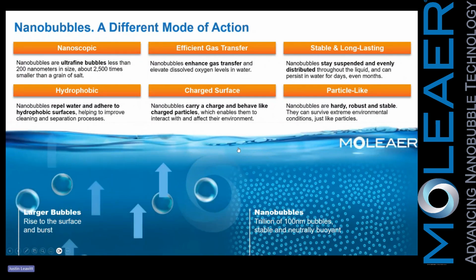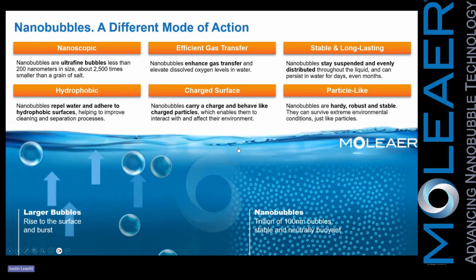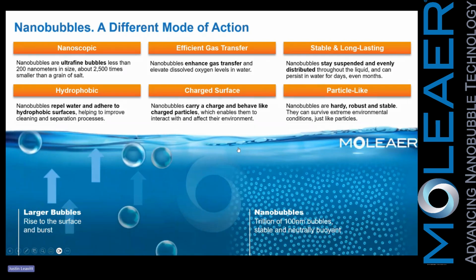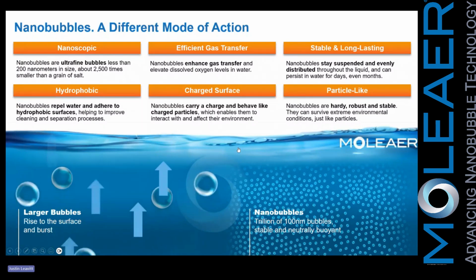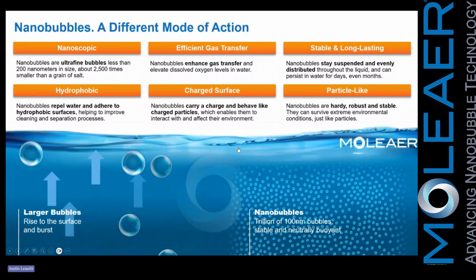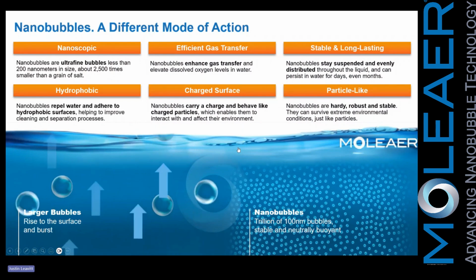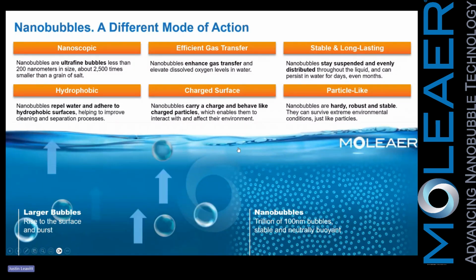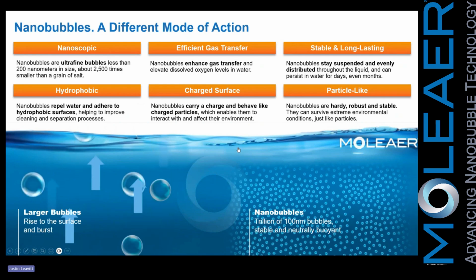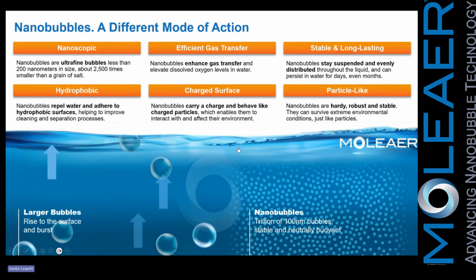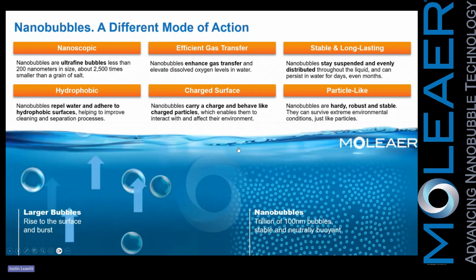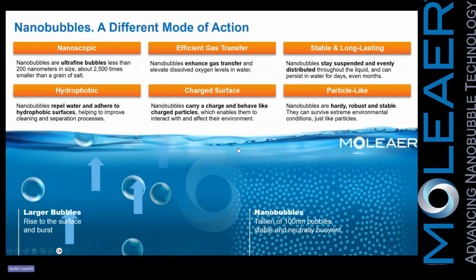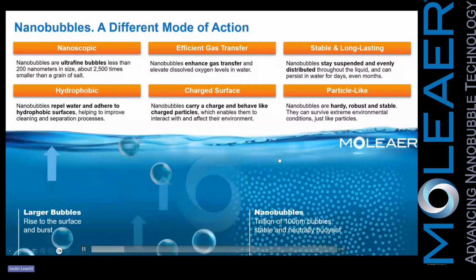So they act like a charged particle. They're stable, long lasting, and hydrophobic. So they're repelling from water, sticking to hydrophobic surfaces like irrigation piping. And they're also incredibly effective at enhancing gas transfer, right? Whether we want to dissolve a lot of oxygen into water or a lot of ozone into water, nanobubbles enhance that gas transfer. Today, we're going to try and really stay on topic and talk about biofilm and not so much about dissolved oxygen and other aspects of nanobubbles, but understand there are a lot of unique characteristics that help utilize successful watering.